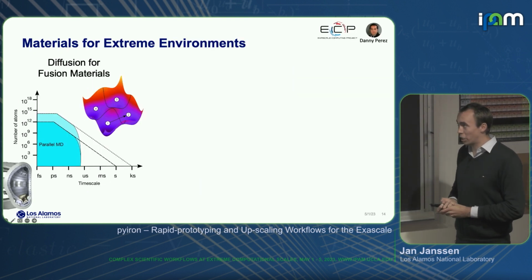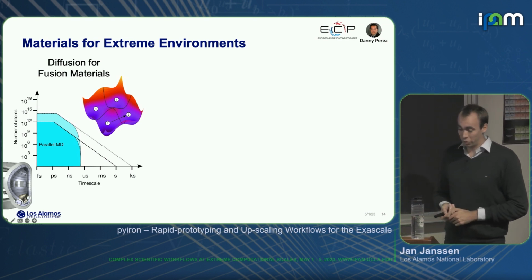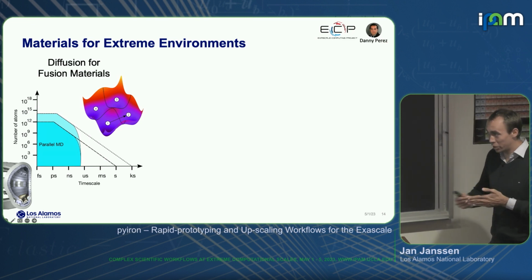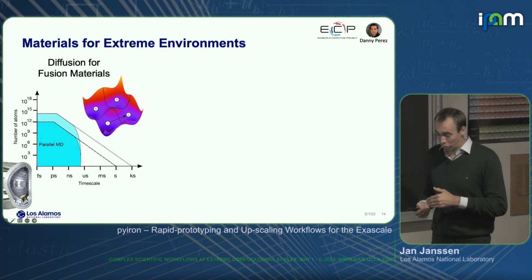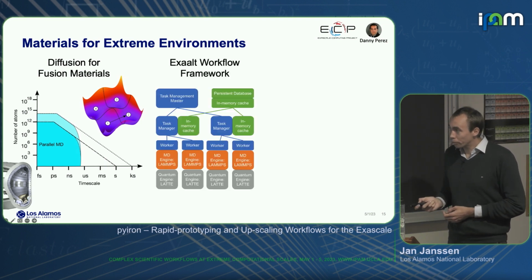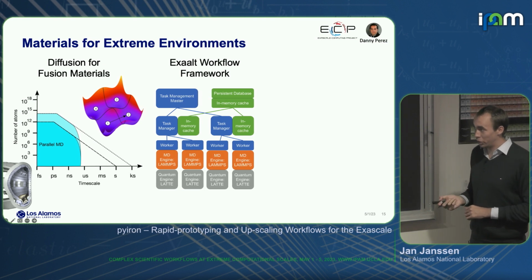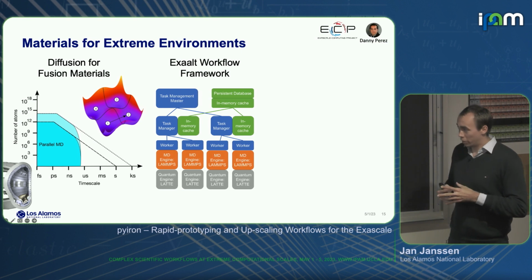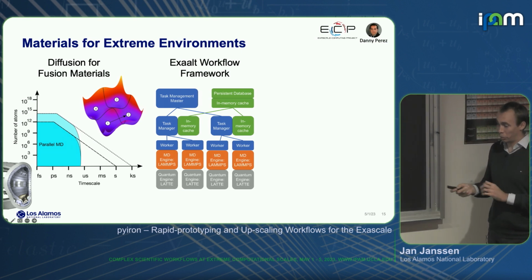And when I came to Los Alamos, that's something that's also there when looking into materials at extreme environments. Right? So Danny is really an expert at extending the time scale of molecular dynamics trajectories, which is very useful, pretty much required to understand diffusion, in particular in fusion materials. And this also results in rather complex simulation protocols as illustrated here, right? So in the Exascale framework, to splice the trajectory and connect them all, we run multiple workers, all running individual snapshots of the MD calculations, and bring this all together.